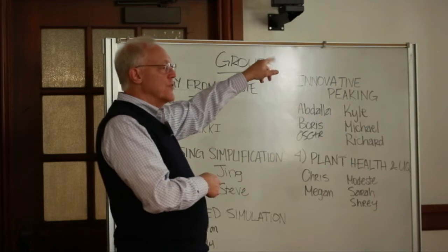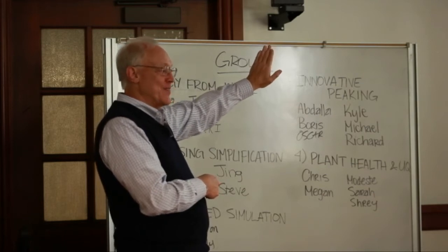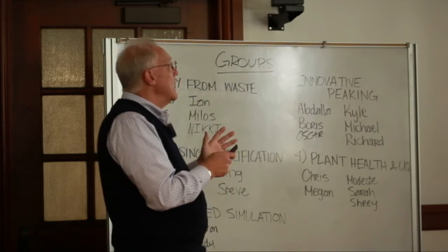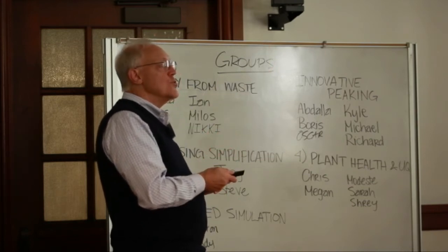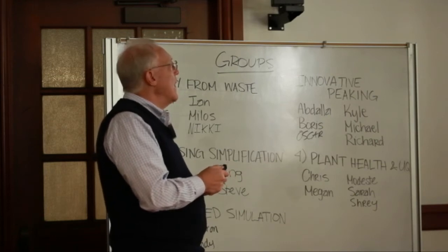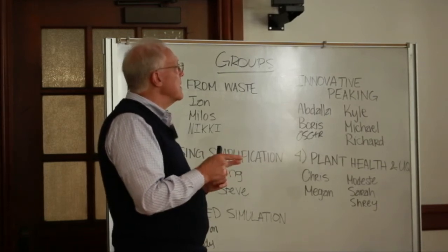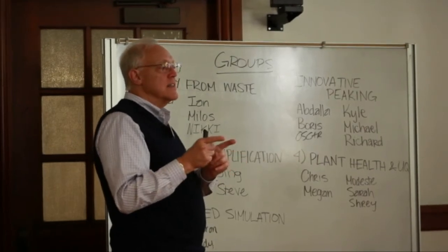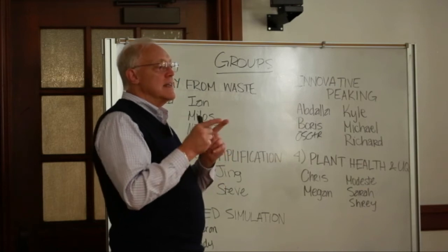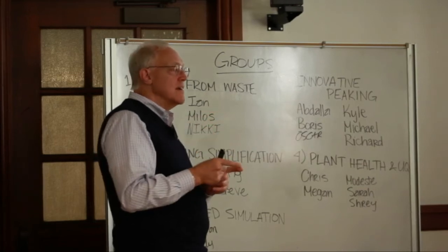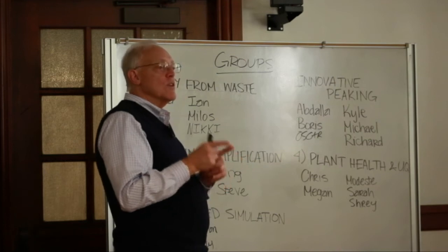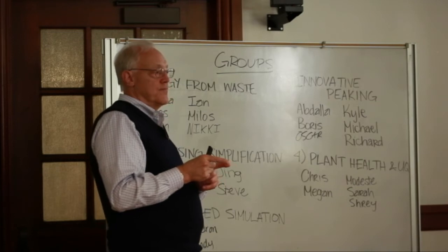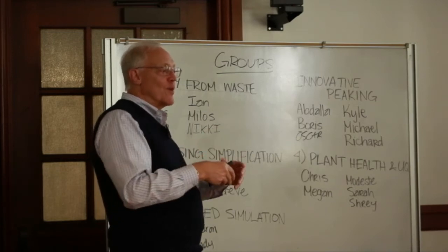I'm not suggesting these have to be your list. This is my list. Okay? But intrinsic safety says, how do I ensure that I minimize the possibility to eliminate my capability to remove decay heat? How do I make it so it's vanishingly unlikely that I will lose decay heat removal capability in a plant? Now, I told you earlier, I'm a proponent of gas-cooled reactors.